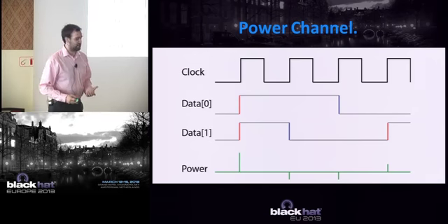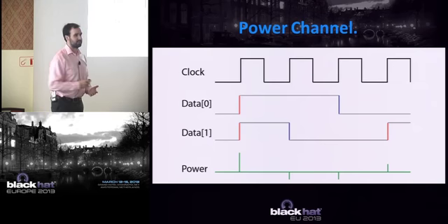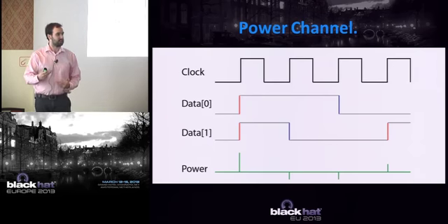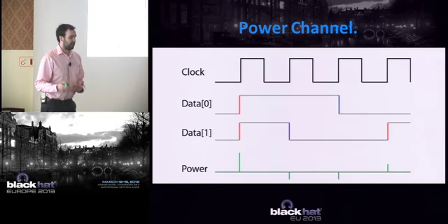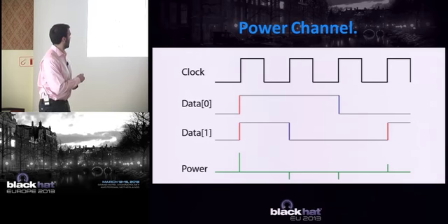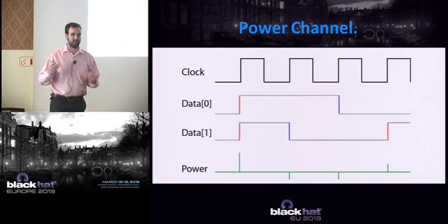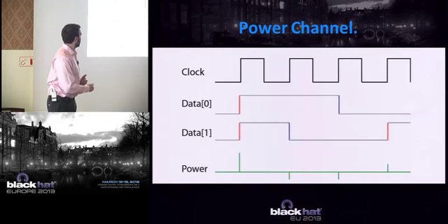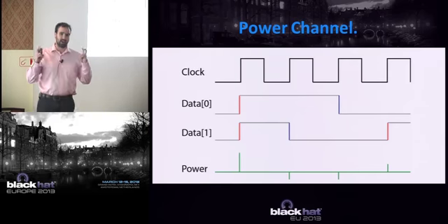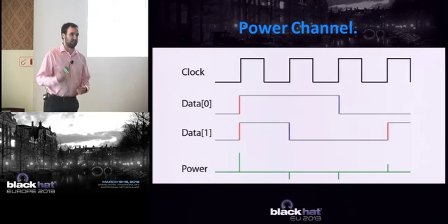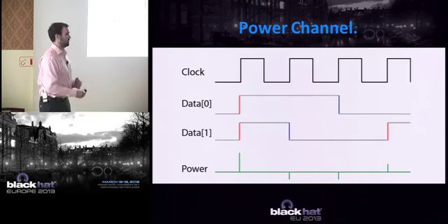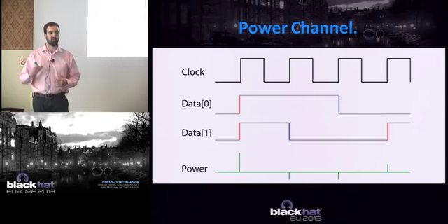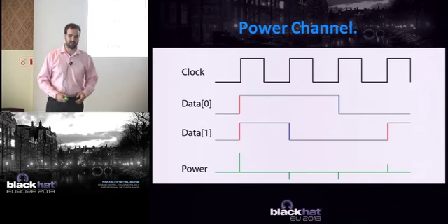So we can imagine that if the data bus is first at the 0 state, and I want to move it to the 1 state, at that clock edge, it's going to take a tiny bit of power to do that. It's just physically required to change the charge on the bus. It takes this power. So if we looked at the power in an ideal manner, what you would see is on each clock edge, you would see some spikes, either in the VCC rail or the ground rail, depending what the state is.